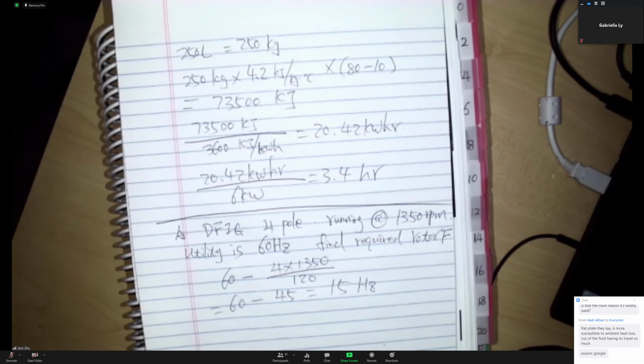But the evacuated tube needs that vacuum to keep good heat insulation. Over a long period of time, maybe 10 or 15 years, the vacuum will gradually reduce and the tube will need to be replaced.